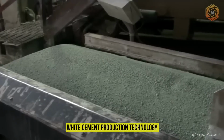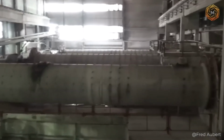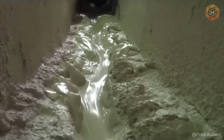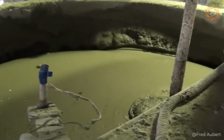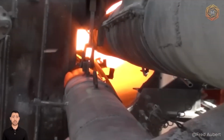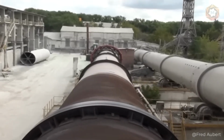White cement production technology. Speaking today on such a complex topic, it is impossible not to separately mention the issue of production of such a non-standard material. White cement, the production of which is moderately different from the technology of the gray product, can be produced both wet and dry. The main difference in technology is that the raw material is subjected to firing at a very high temperature of more than 1,000 degrees, and then quickly cooled with water.